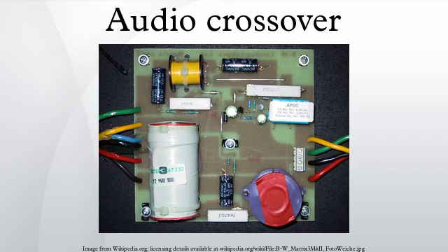Active. An active crossover contains active components in its filters. In recent years, the most commonly used active device is an op-amp. Active crossovers are operated at levels suited to power amplifier inputs, in contrast to passive crossovers which operate after the power amplifier's output, at high current and in some cases high voltage. On the other hand, all circuits with gain introduce noise, and such noise has a deleterious effect when introduced prior to the signal being amplified by the power amplifiers.